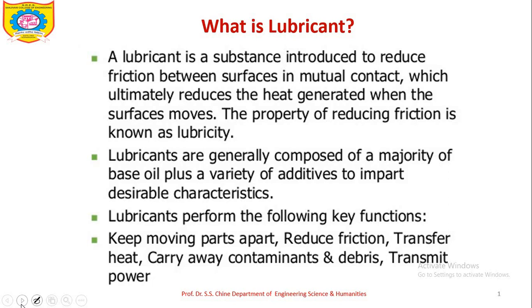So what it indicates is that without application of those oil droplets, there is somewhat friction, somewhat resistance, and the lock is not working properly. But when we put some drops of oil, there will be smooth movement of the shaft of the lock.